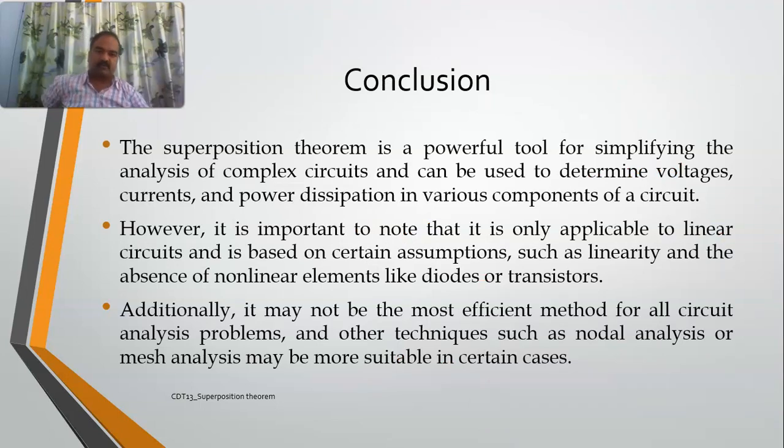Superposition theorem is a very powerful tool for simplifying analysis of complex circuits. In particular, it is very helpful when you want to determine the contribution of individual sources. But there is a problem: it is applicable only to linear circuits. If there are any non-linear elements in the circuit, then this superposition theorem fails.